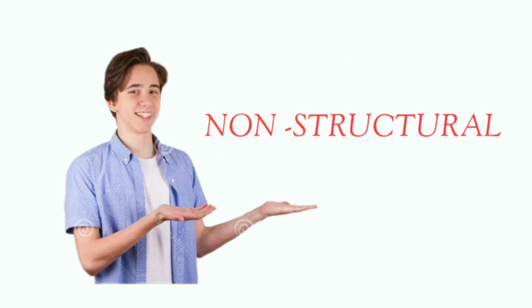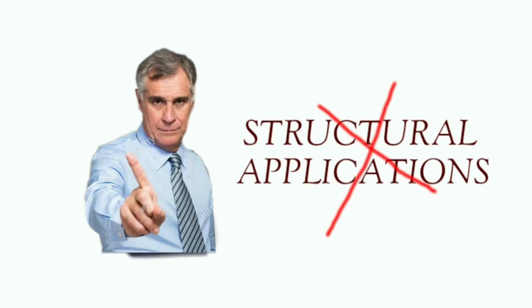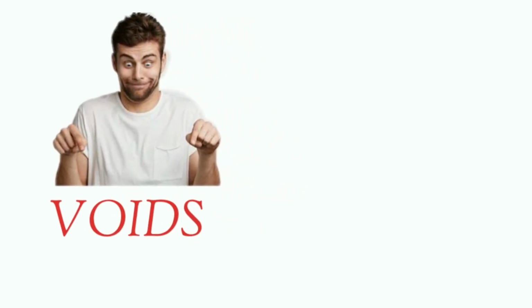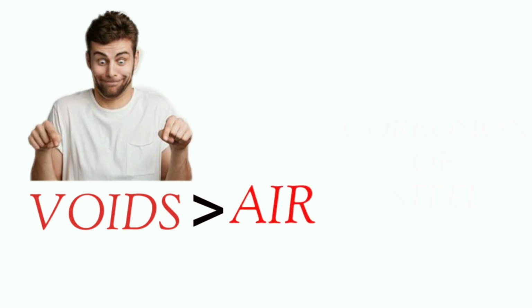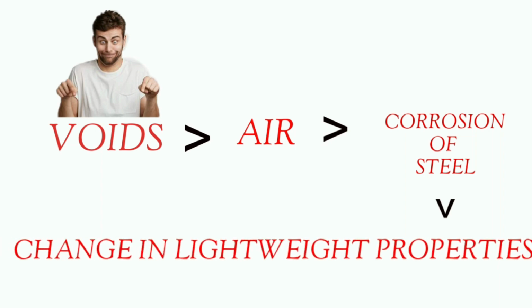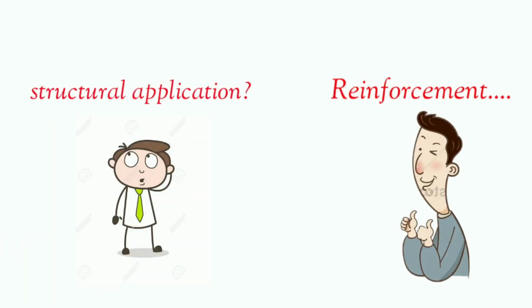They are generally used for non-structural applications like void filling and other repair works, and not widely used for structural applications, as normal reinforcement like steel cannot be used in foam concrete since it contains voids with air which will corrode the surface of the steel, and at the same time the lightweight properties of foam concrete also change. So there is a need for providing reinforcement for applying this in structural uses.